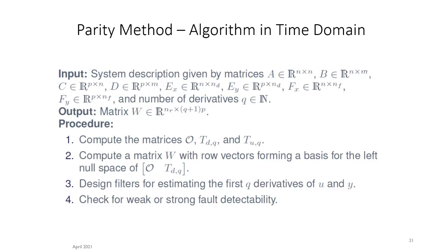And if we need to continue and differentiate more, it would be even more of a problem, because the second derivative is hard to do. So what we need to do is design a filter, especially for Y. As I said, U is not problematic because it is not noisy, but for Y, we need to filter the signal and then differentiate.